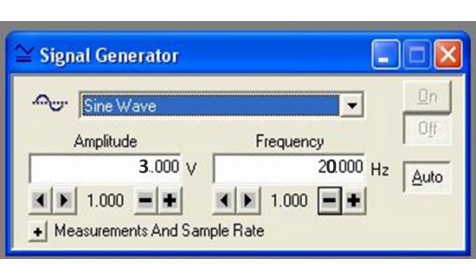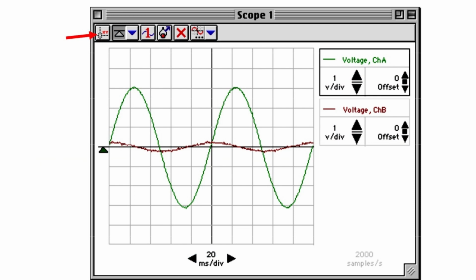6. Adjust the function generator to 20 Hz. Repeat the process to find the new value of voltage and record it in table 12.2 next to 20 Hz. 7. Increase the frequency in 10 Hz increments until 150 Hz. Repeat the process of using the Smart Cursor to find each new value for the resistor voltage, VR. Record each voltage value in table 12.2.